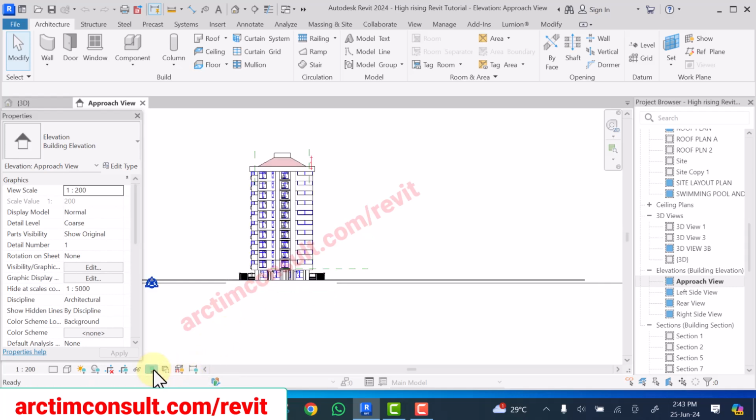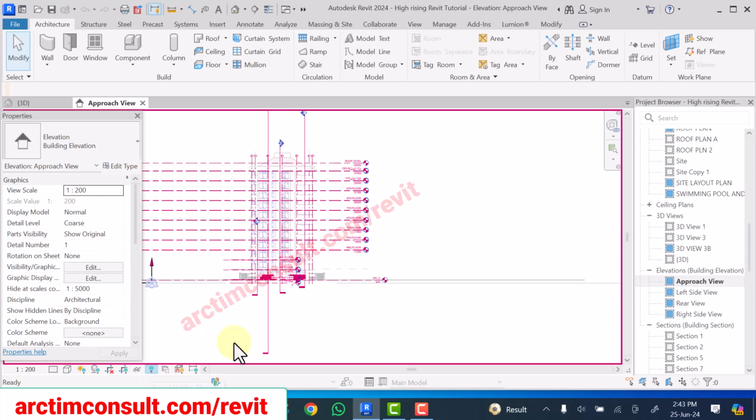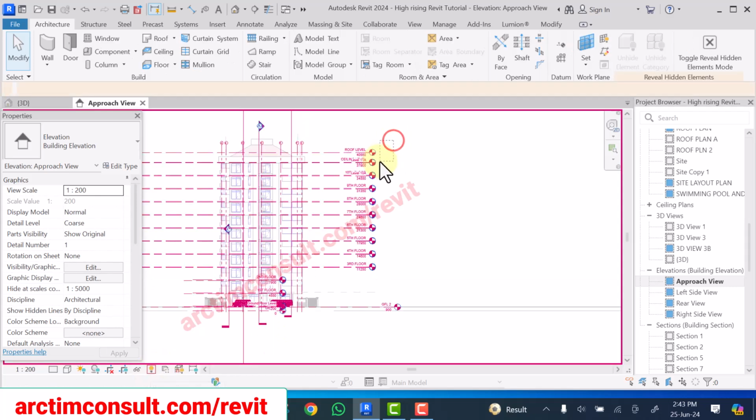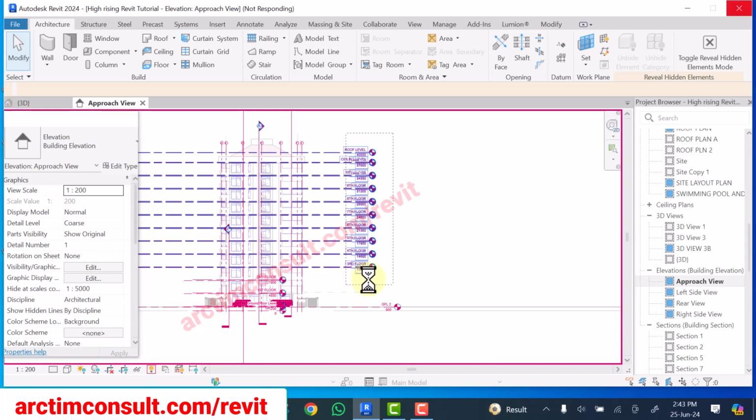headrooms. So let me click on this to unhide some of the things that I've hidden in the project before, and one of those things are the levels. So I'm going to unhide the levels now so that we can create our own from here.